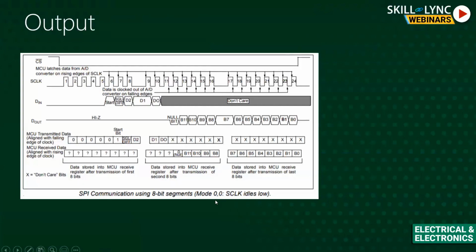So one more example I would like to mention is for the SPI based ADC. I have given the same example. Let's consider the 12-bit ADC, the MCP3204. In the datasheet, they specify everything: the different timing parameters we need to consider, what values we need to put on the input line and output lines, and how we will get the data.